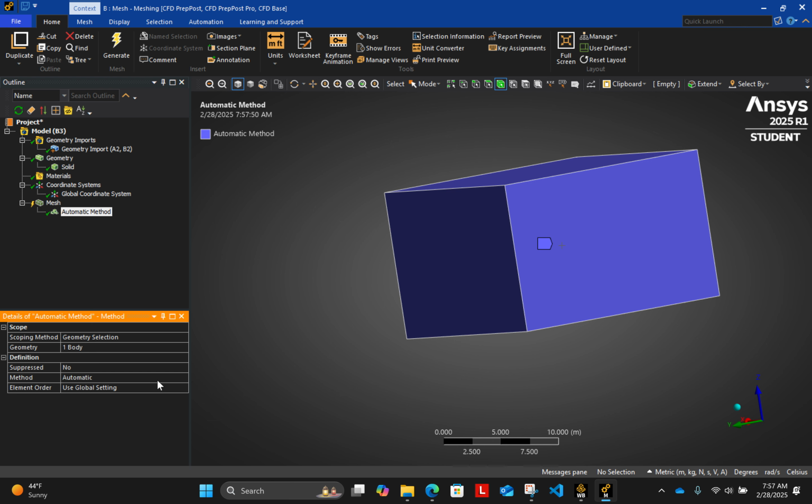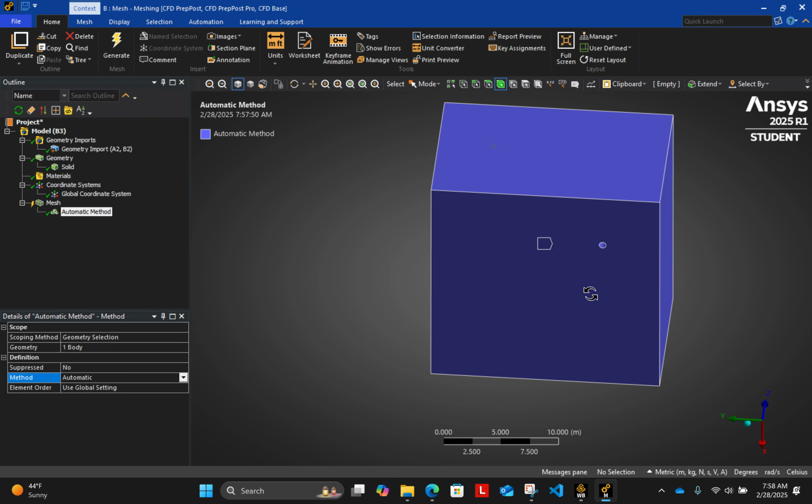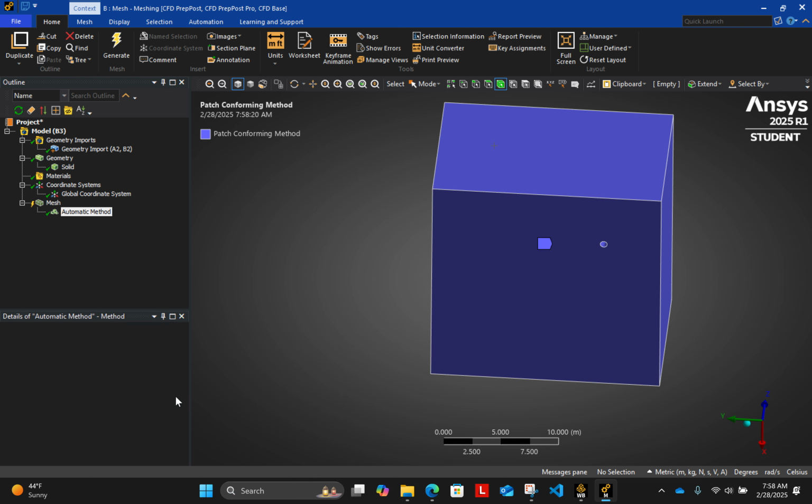Is it, again, quadratic, triangular, hexagonal, different types of mesh. This is not a very structured geometry, so we shouldn't really use a square mesh. What I'm going to do is use tetrahedrons, essentially similar to triangular meshes.